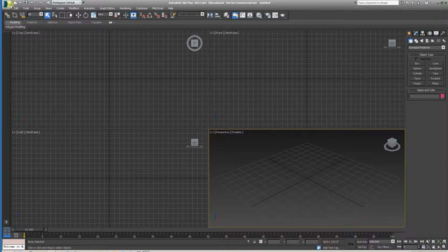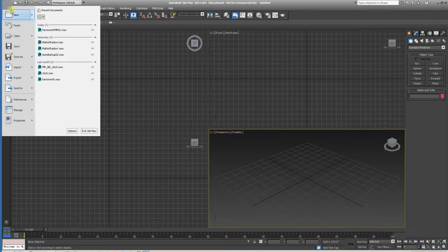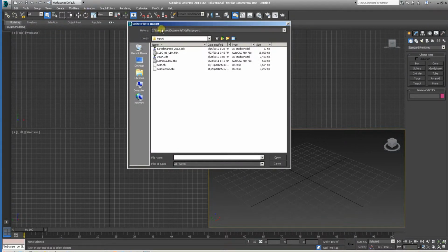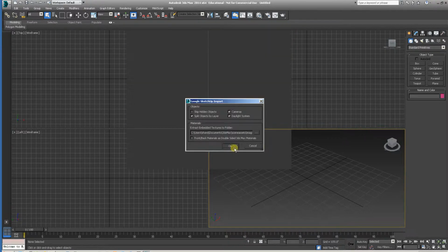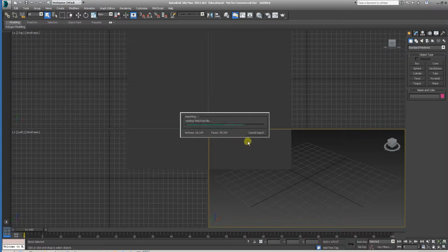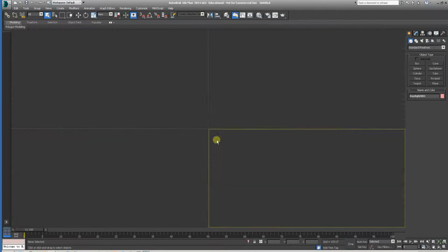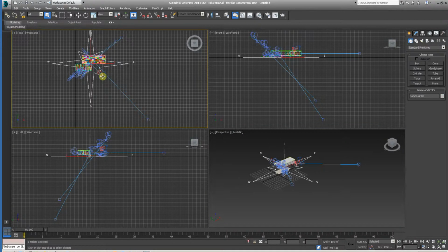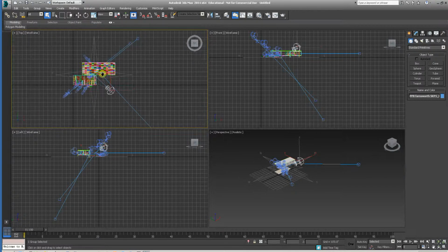So instead of a file button, they have a button. So it's the same thing, all your typical new, open, save, import will be in here. So I'm going to go ahead and import the Sketchup file. Hit open. Go ahead, leave the defaults, hit OK, and hit yes here. It's coming in with a daylight system from Sketchup, which I will delete just to cleanse and give one that's from this version of 3dsMax for a little more reliability. You never know. There's a difference.